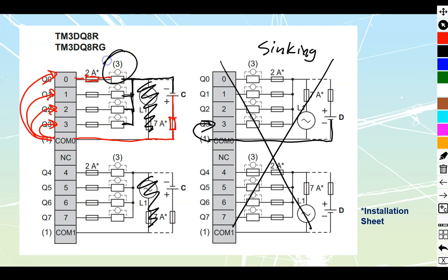There is also a note on the data sheet, and this note shows that our load has a little device connected across it. That's just to help maintain the integrity of our relay contacts. It's going to be used to suppress any little bit of inductive kick that we would get off of them. Okay, so we're going to be working from this drawing, translating it now down onto the physical.